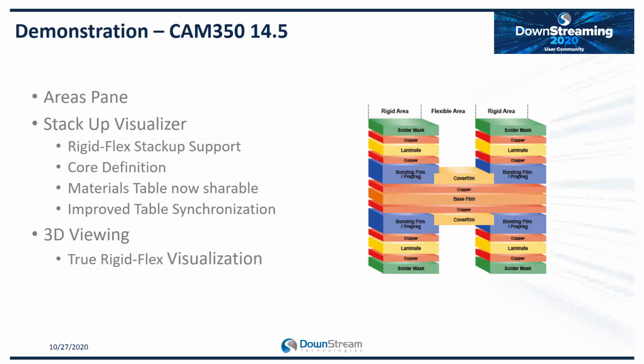Okay, and a follow-up to that. You showed or talked about how you could create the stackups and stackup zones over on the CAM350 side. Is CAM350 required, or if you're just trying to document this, can all of this be done in Blueprint? That's correct. If you get the proper file format, you don't need CAM350 as a precursor to Blueprint. That's correct. If the data comes in correctly, right?